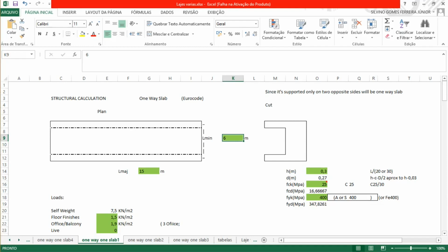reinforced concrete bricks or some beam. So to calculate the total depth we can use this equation, L by 20. This will help control the cracking and the deformation, so it will help in many problems.